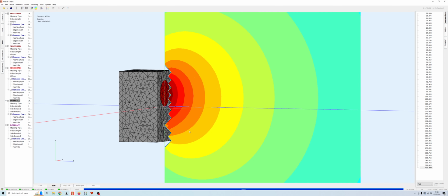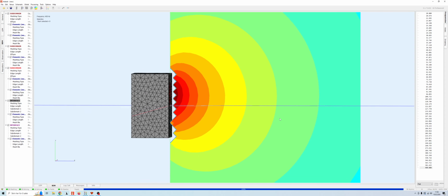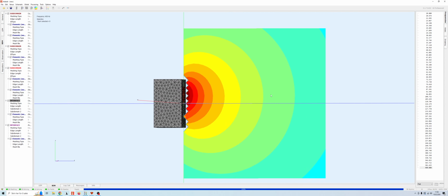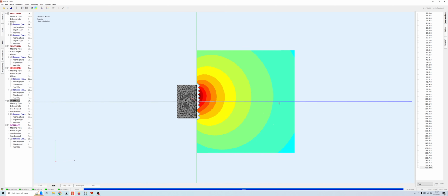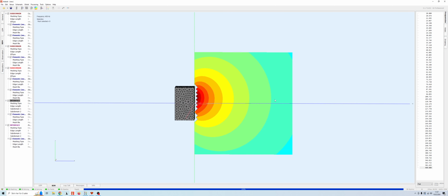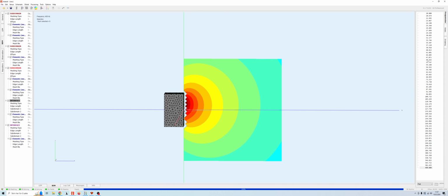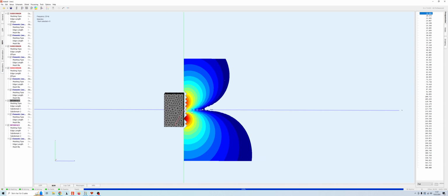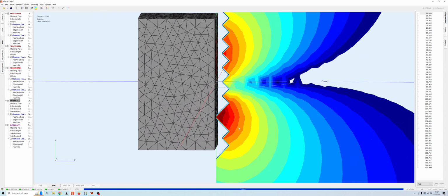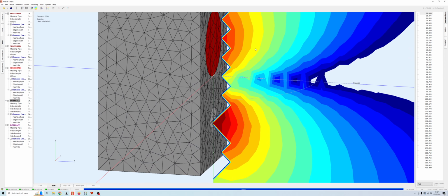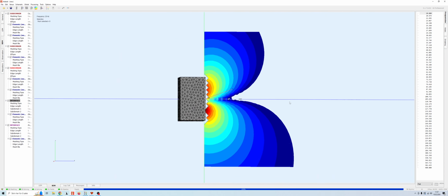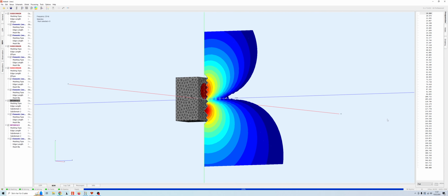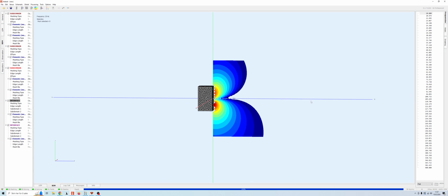There's not really much output from the port. The driver is where the output is from, and we can see that it's quite smoothly radiating in all directions. And then if we look at very low frequencies, say 20 hertz, here we can see that in the near field, there is plenty of output from both the port and from the driver, but they combine, and the resulting sound output is very low as you move away from the loudspeaker.